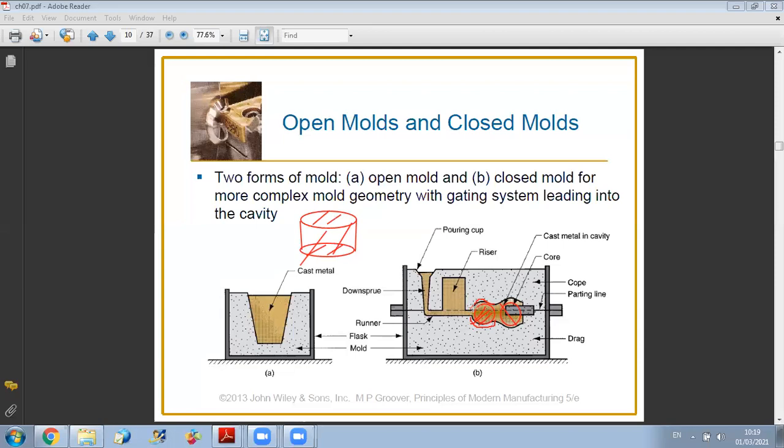You can also take one average, but it will not be a good representation. You can take the whole solidification time by considering, for the whole shape, the total volume over the total contact area. So the total contact area is this one, like this, like this. You should account for this whole area. Of course, if I consider constant depth, I multiply the perimeter by the depth. Okay.